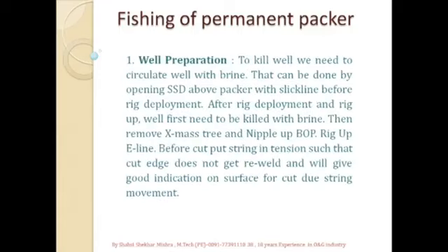So in the well preparation, to kill the well, we first open the SSD with the slickline, and if we are not able to open the SSD, we puncture the tubing.